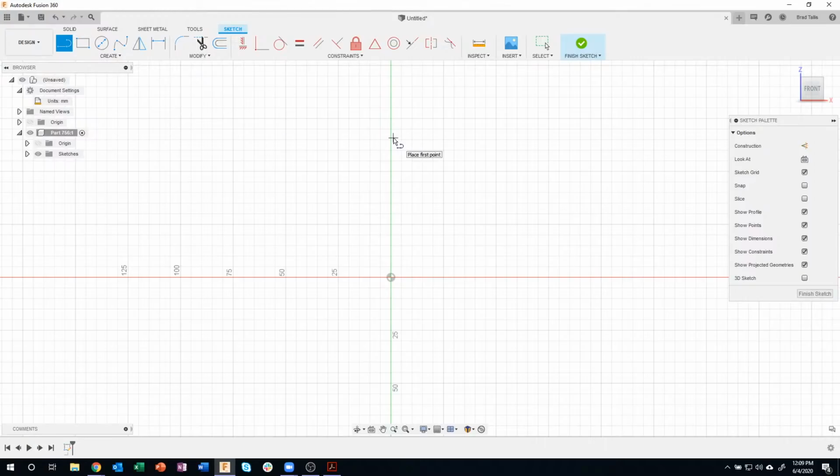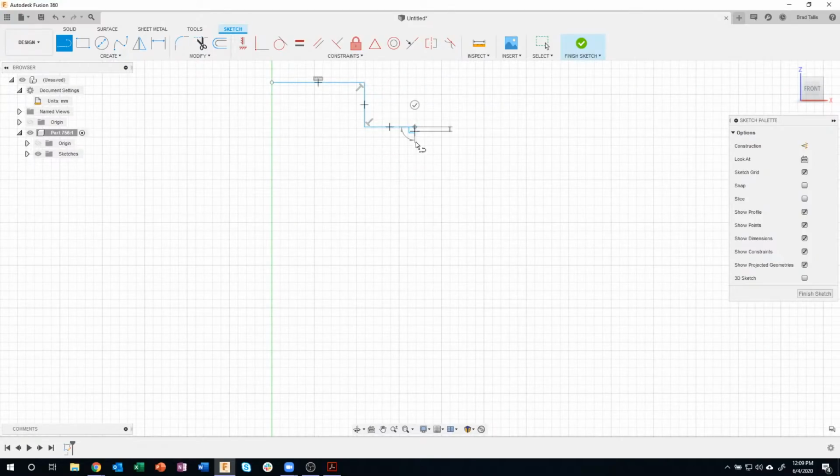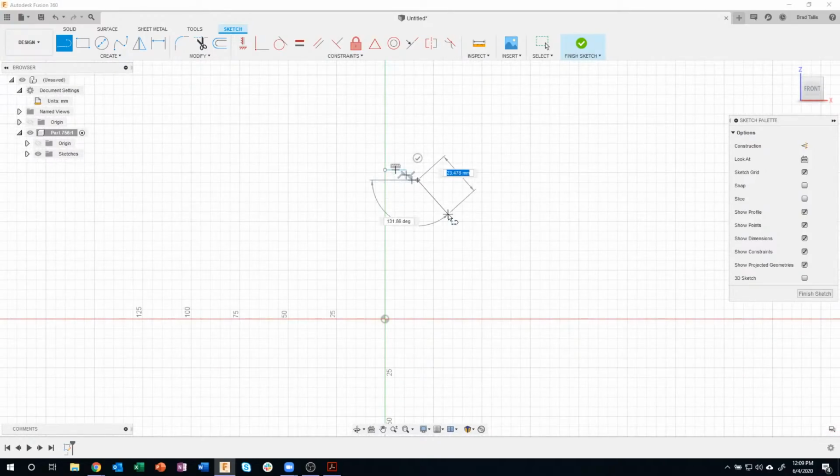So I'm going to basically hover over this center point here, or the starting point, and you'll see, it's kind of hard to see, but there's a little snap guide that sort of appears. And so it's basically saying you're right above that 0, 0. So I'll come over a little bit, I'll come down a little bit, come over, and now notice like that green checkbox is kind of in the way. So if I were to click right now, it would actually end my selection. So I might want to zoom up just a little bit to get that checkbox out of the way.